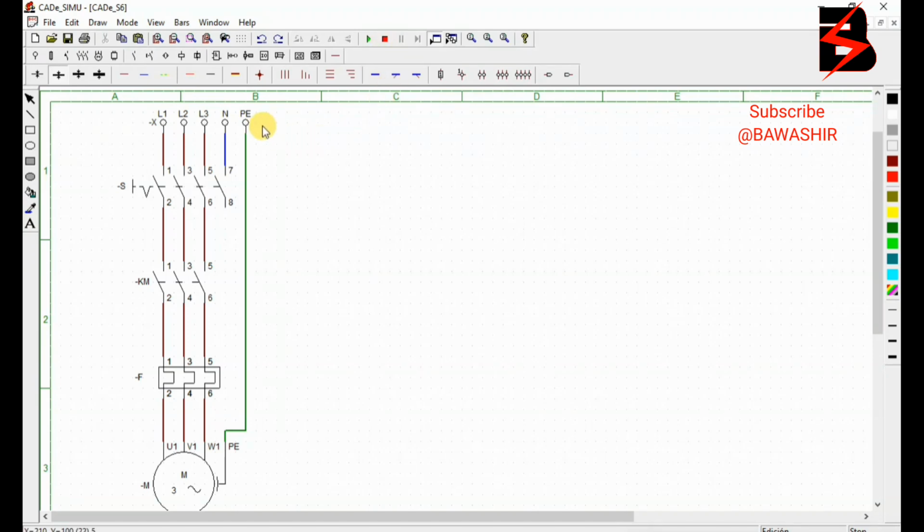We are going to use the very power from the power line, from the power circuit. So we are just first going to have our control breaker here, our 2-pole control breaker. Then from there, oh sorry, this is a contactor, so delete, 2-pole circuit breaker.